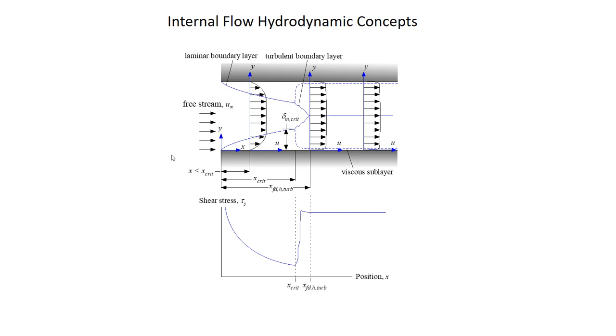So I guess one last picture that hopefully helps with this is, if you have a situation where the Reynolds number is substantially higher than 2,800, you would expect that you transition to turbulence, and it's a turbulent flow. So what would that really look like? If you look at the developing region of the flow, you would still expect that initially you have a laminar boundary layer that grows, right? Because it takes some time before you transition to turbulence, right?